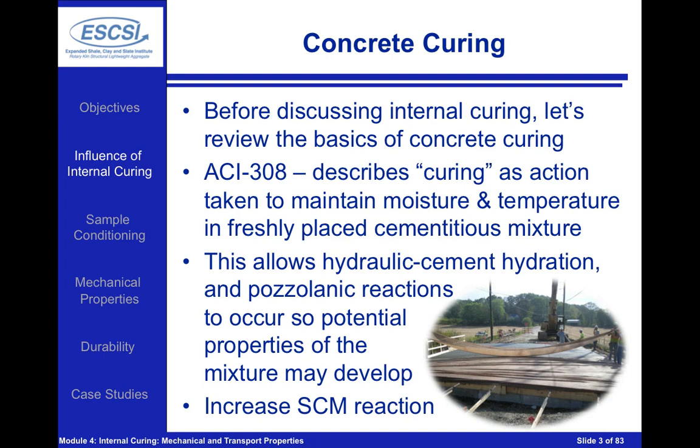Now ACI 308 describes curing as an action that's taken to maintain moisture and temperature in freshly placed cementitious materials. The idea behind internal curing is we're going to use some sort of a material inside of the concrete mixture to really help to maintain the moisture, to make sure that the system stays with a high moisture content.